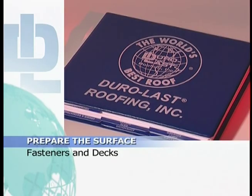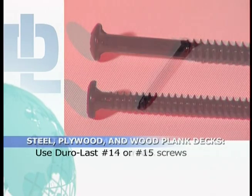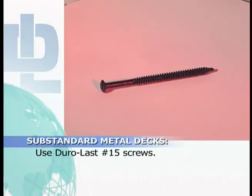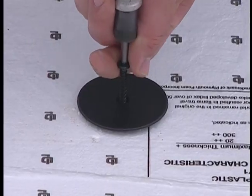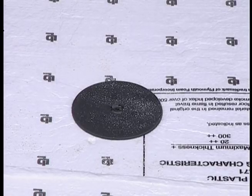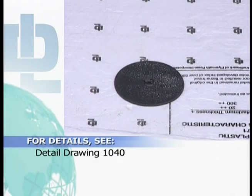We'll cover this generally here. For complete fastener requirements and details, refer to the Duro-Last specification manual. For steel, plywood, and wood plank decks, use Duro-Last number 14 or number 15 screws. For a substandard deck, it may be beneficial to use Duro-Last number 15 screws. Pull tests will verify proper screw selection. You must drive the screw straight in, not at an angle, and penetrate a minimum of 1 inch from the deck's top surface. Seat the screw head firmly into the plate, being careful not to over or under drive the fastener. For details, see Duro-Last drawing number 1040.